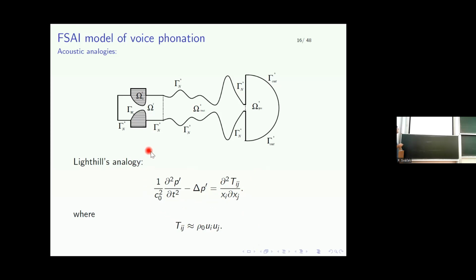Okay. We might just mention that for the acoustics we also need to include boundary conditions, and usually the sound hard boundary condition is used on the wall, which means that the acoustic propagation is fully reflected at the surface. This is in principle a Neumann boundary condition, which can be used on all the walls. But here we have some representation of the mouth, and the signal goes out to the free space, and we don't want to reflect the sound waves on this part of the boundary. So in this case, we either use the Sommerfeld boundary condition in our implementation, or Jan Volášek is also using software from Manfred Kaltenbacher from Graz, which is based on a perfectly matched layer, so we add the perfectly matched layer there.